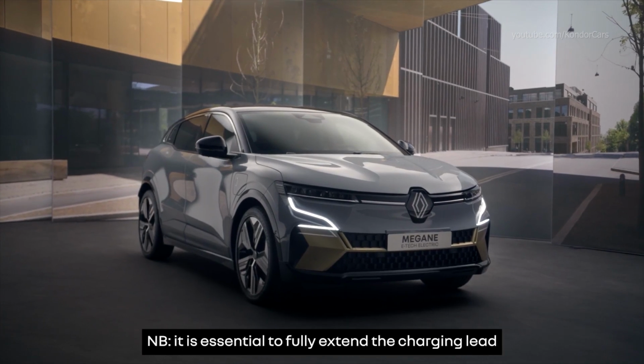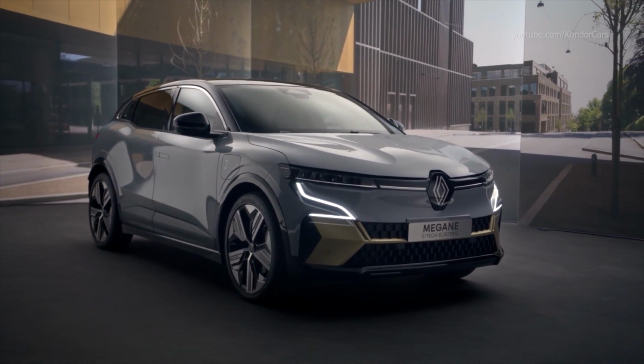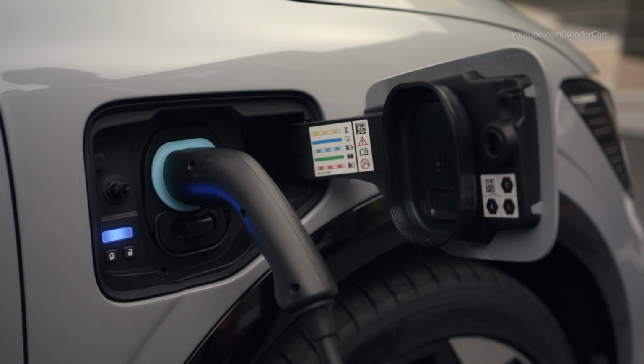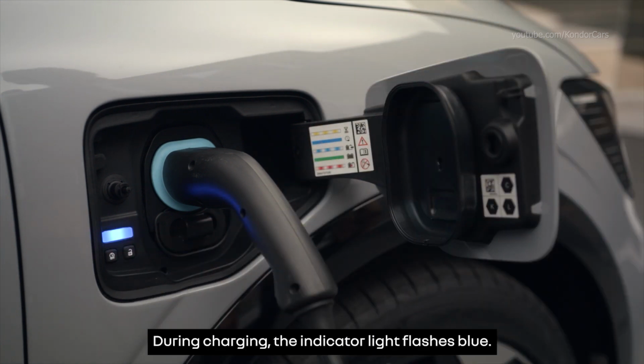Please note, it's essential to fully extend the charging lead to reduce heating. If the indicator is a steady blue color, it means that a charge has been scheduled. To start a charge, immediately press this button. During charging, the indicator light flashes blue.